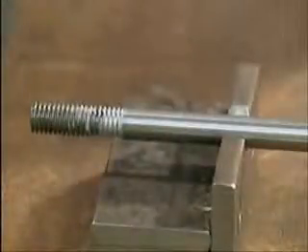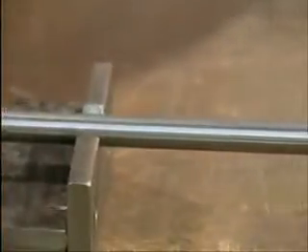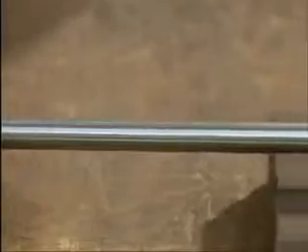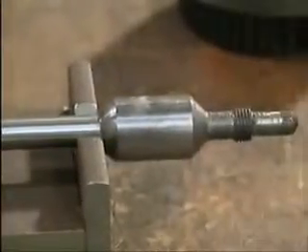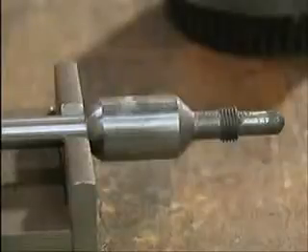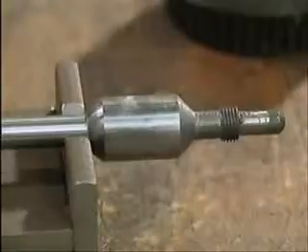It's also important to check the straightness of the valve stem, because a bent stem is a common cause of valve malfunctions. A bent stem can prevent a valve from opening, or it can keep an open valve from reseating properly when system pressure returns to normal. Two common causes of bent valve stems are careless handling and improper gagging.